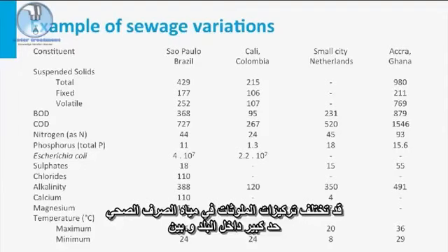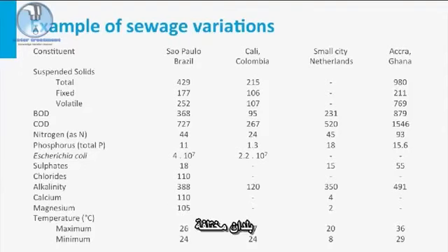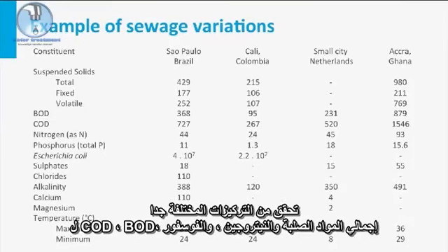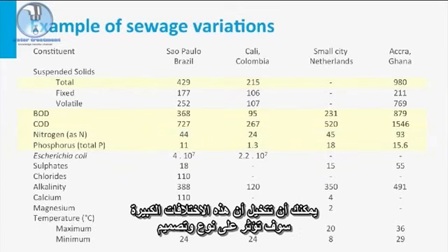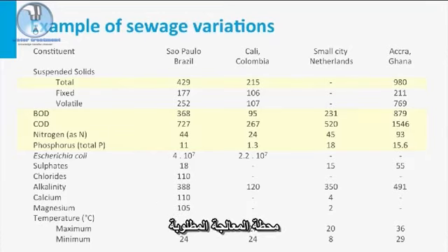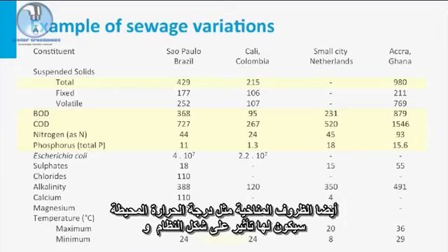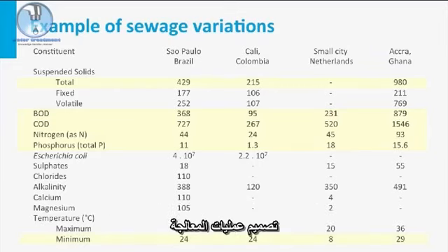Pollutant concentrations in sewage may largely differ within a country and between different countries. Check out the very different concentrations for COD, BOD, total solids, nitrogen and phosphorus. You can imagine that these large differences will impact the type and design of the required treatment plant. Also, climate conditions, such as ambient temperature, will have its impact on system layout and process design.